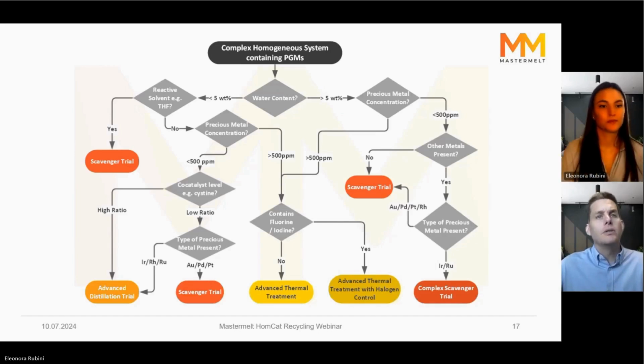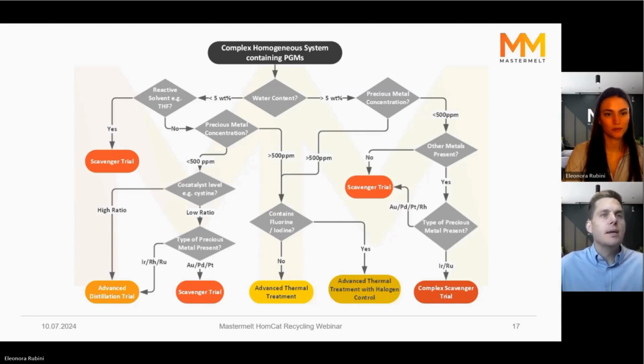And here we'll introduce a number of different scavengers, various different processing parameters, and look at which has the best recovery over time, and the quantity that is recovered in that time frame, to see where the optimum level is. We don't want to be over-processing the material to chase those final few grams of palladium, so we have to look at it and analyze where's the right time to stop the processing.